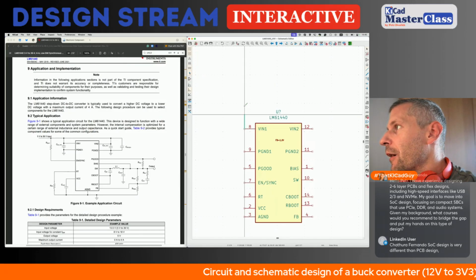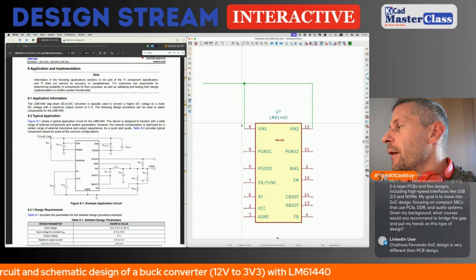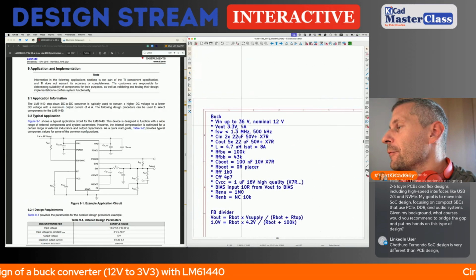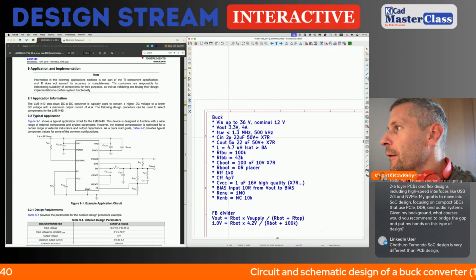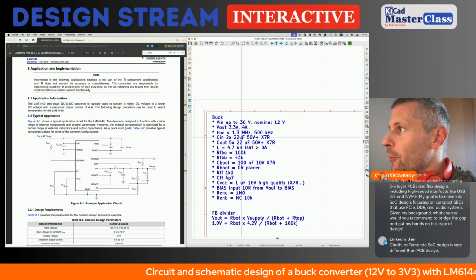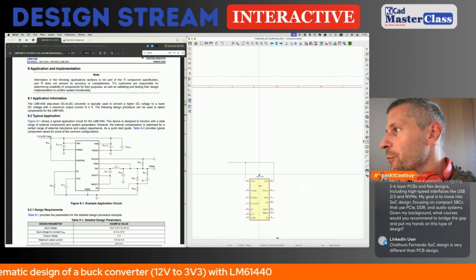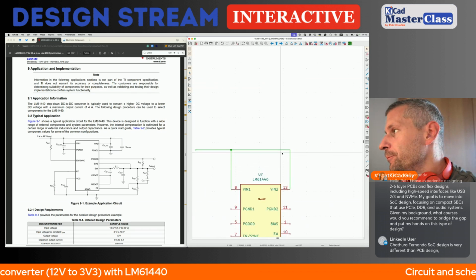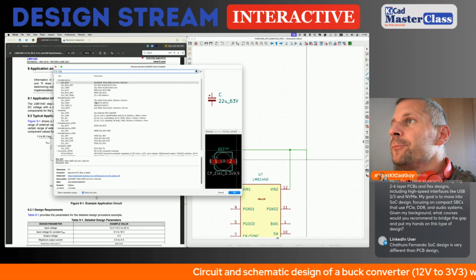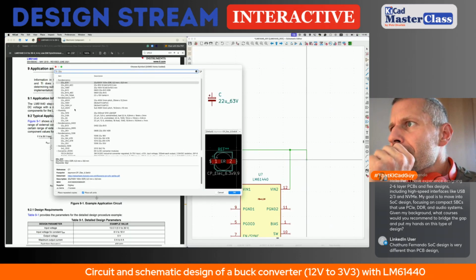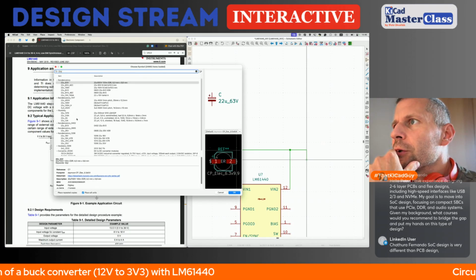As I said, there are two power entries to the switcher, and we said that we need to use two 22 microfarad 50 volt plus high quality capacitors at the input. So this will be input, and at each power entry point there will be one capacitor. I say 22 microfarads, 50 volts or more.